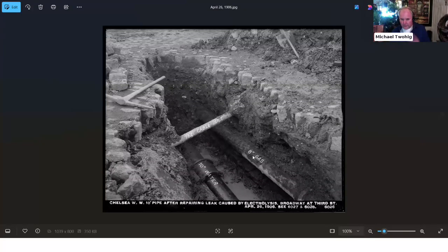So like exactly, Paul, we talk about some of these lines, these water and gas lines. These have all been either abandoned in place if they're small systems, and the metal didn't last. So they would have corroded away in time. The owner would have gone in and put new utilities adjacent to these existing systems. So for many projects we look at, the existing facilities are the new systems. They've forgotten about the abandoned systems in place. And some of these are very problematic, because what looks like white space on some people's drawing and maybe room for a designer to build a new line, we find that is already cluttered, and there's already other things in there. In this case, I guarantee these 8 and 10-inch pipes are no longer in service.